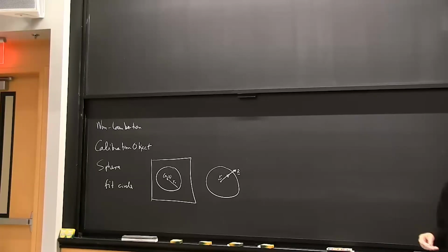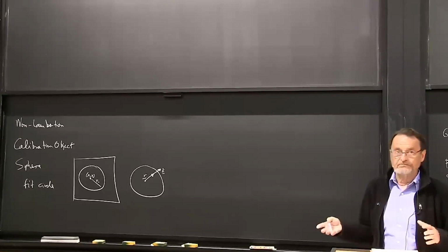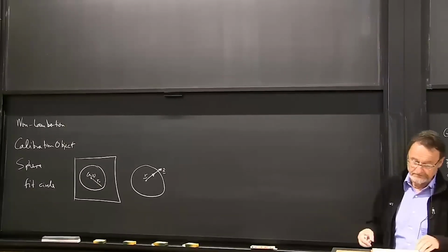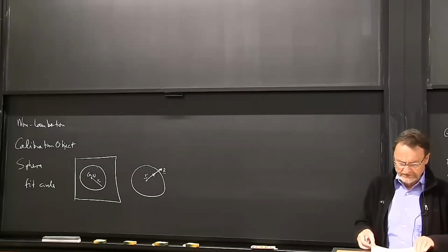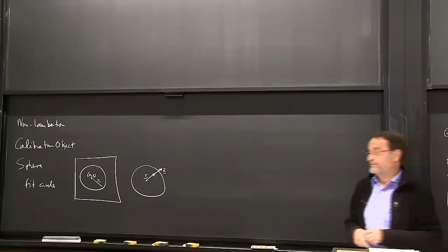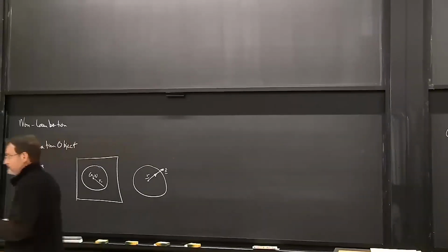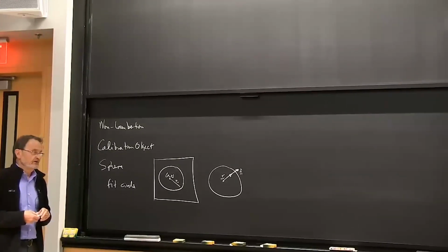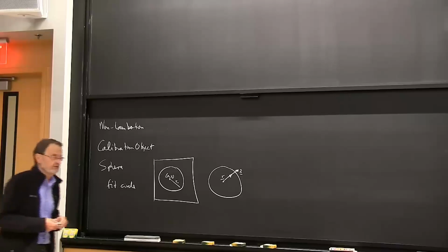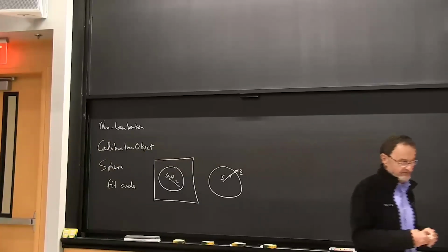Of course, this doesn't quite apply to the Earth because it's not a sphere, so we need to modify that slightly. And that's why there are several different definitions of latitude, depending on whether you're talking about the local surface normal or the vector from the center of the Earth. And usually we take the local surface normal as the definition for the angle that's latitude.